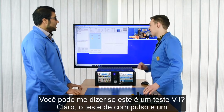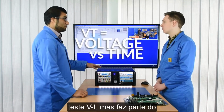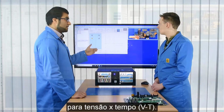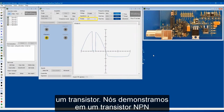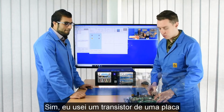Okay, so the pulse output is a slightly different test. It's not a VI test, but it comes as part of the BoardMaster. It's more of a VT test. So we're changing the display from voltage against current to voltage against time, VT. So this test is useful for gate-activated devices, for example, transistors. You demonstrated on an NPN transistor, is that right? Yes. Okay. I used the transistor on one of our boards we got here.